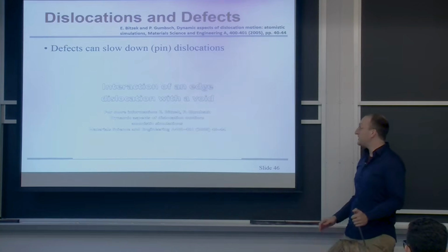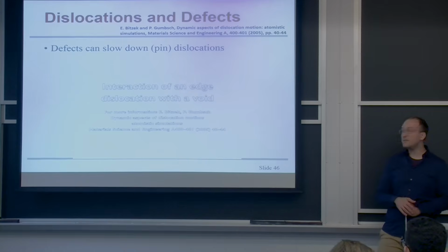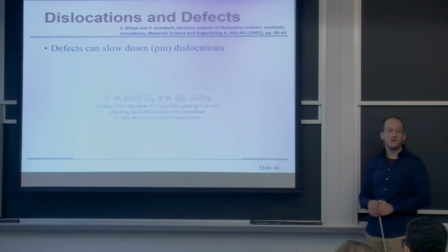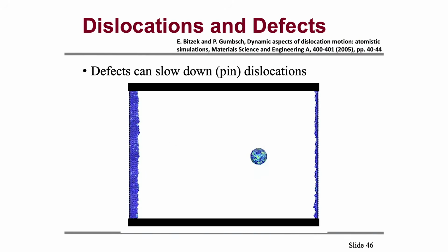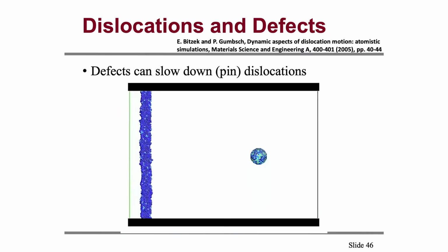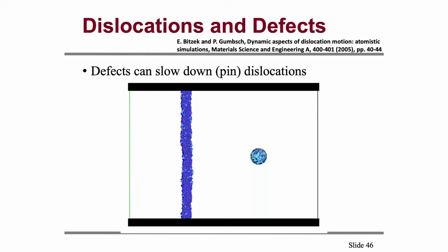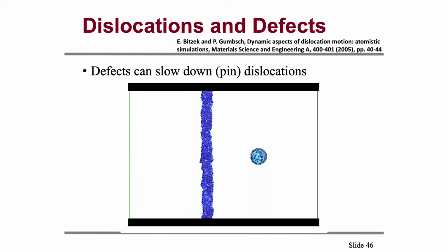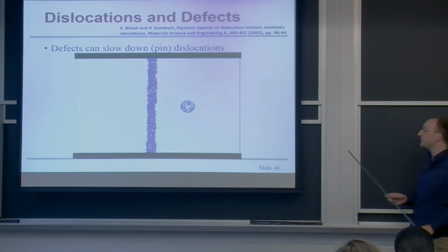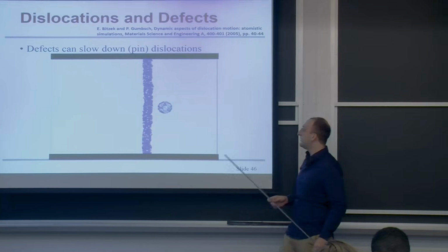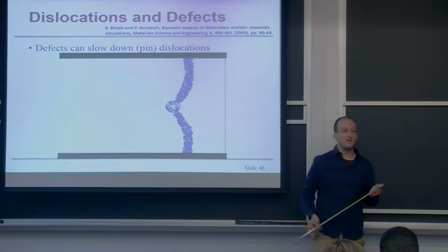And so dislocations and defects can actually interact. Let's say this is the interaction of a 1D defect, a dislocation, with a 3D defect, a void. If you have a material that's deforming plastically very smoothly and isn't going to undergo fracture, you want the dislocations to be able to move. If you put anything in their way, they tend to get stuck.